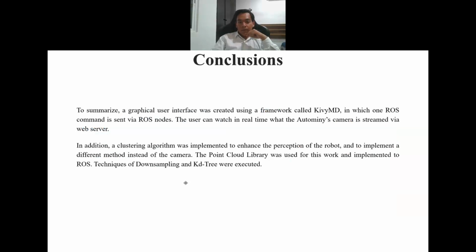To summarize the work, a user interface was created using Kivy, ROS, and Python, sending the information via a ROS node, and the camera was streamed via a web server. In addition, a clustering algorithm was implemented to enhance perception, proposing another method to segment objects, using the Point Cloud Library and applying it to ROS. I think that's all.